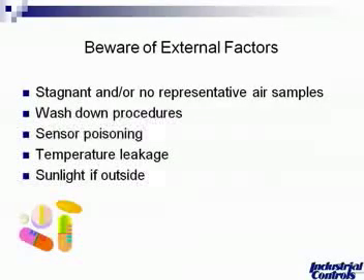If you have a clean room and there are cleaning crews that come in, you want to make sure you have known wash-down procedures. Is the cleaning crew going to slap the humidity transmitter with a mop, or are they going to spray it with a hose? Are they going to use solvents, which could add to sensor poisoning?